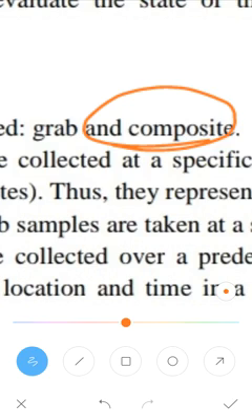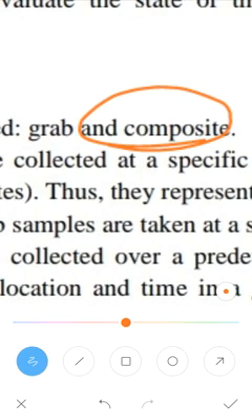The main disadvantages of composite samples are the loss of the relationship between individual samples, dilution of concentrations below the detection level, an increase in the potential for analytical interference, and increased possibilities of analytical interactions. In addition, composite samples may reduce the number of samples below what is required to meet the specified data quality objectives. So in such cases do not use composite samples.